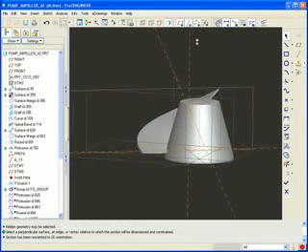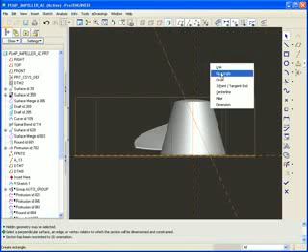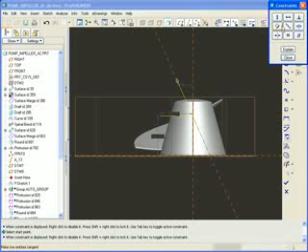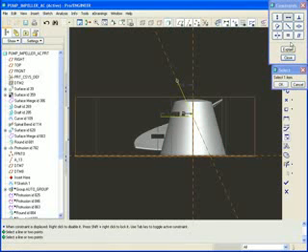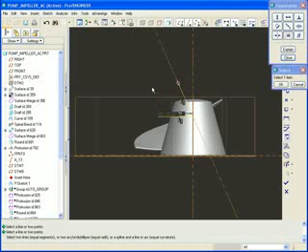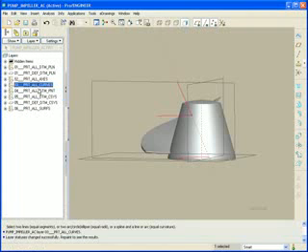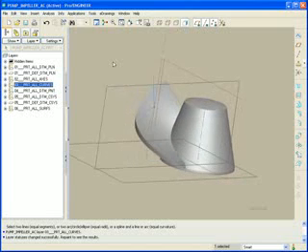Okay, so let's go to the sketch view, and the angle now that I'm interested in is from the horizontal squared up to that plane. Using some geometry references here, we'll specify this is to be exactly horizontal, and we'll just make these two equal to each other, just for grins. Now we have a curve, and they're currently turned off, so let's unhide them. So there is the slope angle that we're interested in.